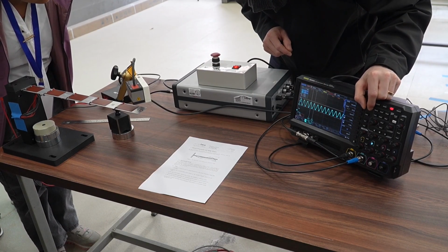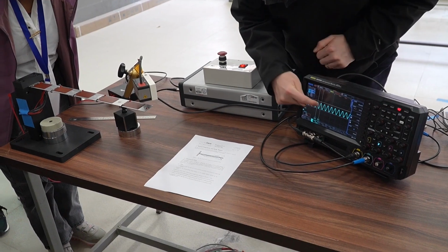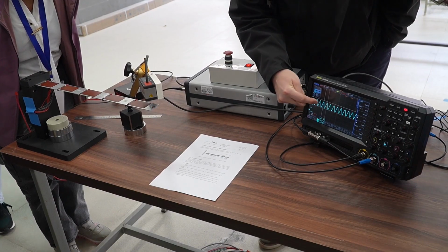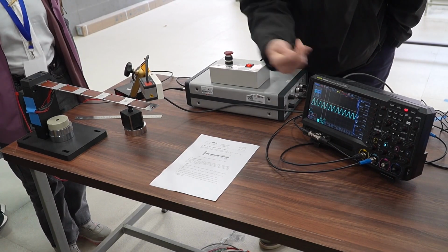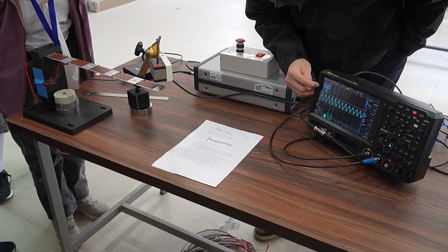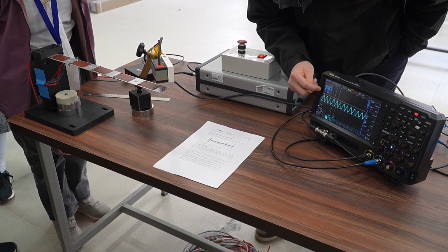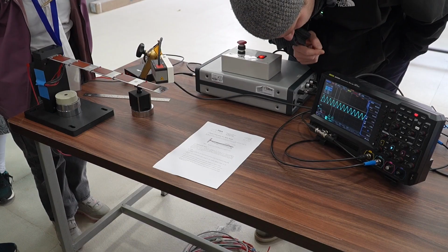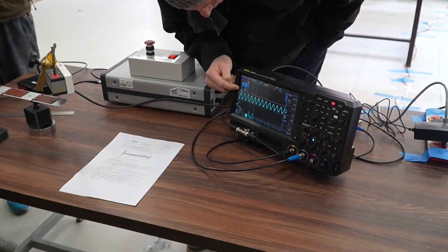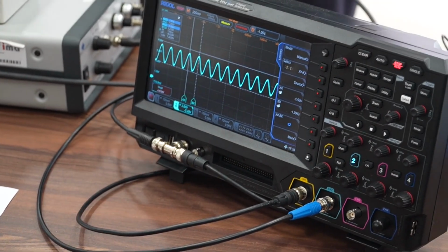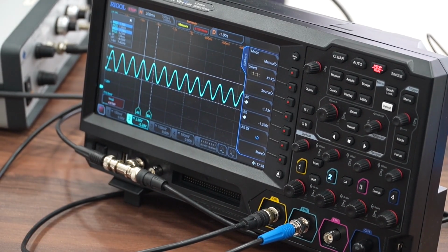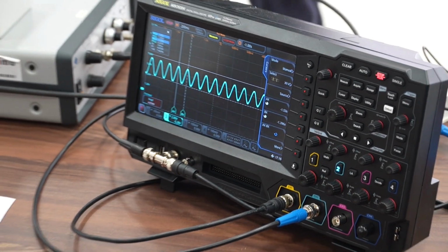Now I can shift the cursors to the peaks. Now the two cursors are on two peaks. If I want to increase the quality of that measurement, I take not one peak but several peaks and divide by the number of peaks, because then the accuracy increases, obviously. And here I can already read that the delta x, so the delta in time, is 1.134 milliseconds, and that translates to 7.462 Hertz. So the first eigenfrequency is about 7.5 Hertz. Now the question is, how do I determine the others?